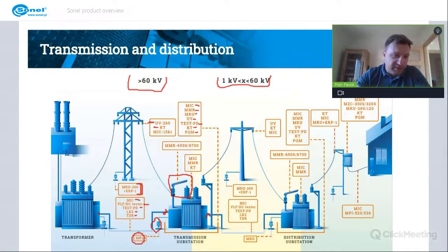So here the whole trick is that when the breaker connector is closing, we can have an arc burning on the connectors for some time. And it can leave the carbon on the surface of the connectors. So we need to make sure that there is a good connection between those connectors, of course, but to get rid of any resistance of the carbon, we need to use the higher currents. So that's why we need to use the meters with higher measuring currents.